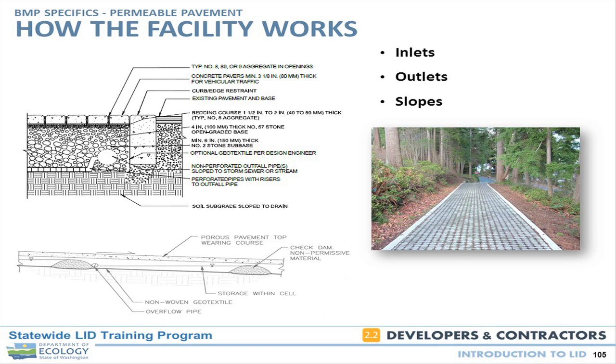And I think that's an important detail, that we don't put under drains under these facilities because that tends to defeat their purposes. But we provide overflow structures so that we don't get water exfiltrating out of the pavement like on a slope. So we want to make sure that we allow there to be overflow but not under drain.